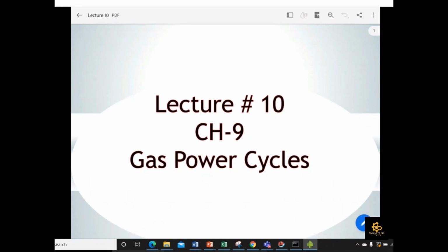Okay, so previously we already talked about some different thermodynamic analysis of the Otto cycle by using two different approaches. We already discussed whether it will be a variable specific heat or a constant specific heat. But whenever we talk about the spark ignition engine, we cannot do all the thermodynamic analysis by using the assumption that there will be an isentropic process, because isentropic expansion and isentropic compression mean there will be no heat involved in it.